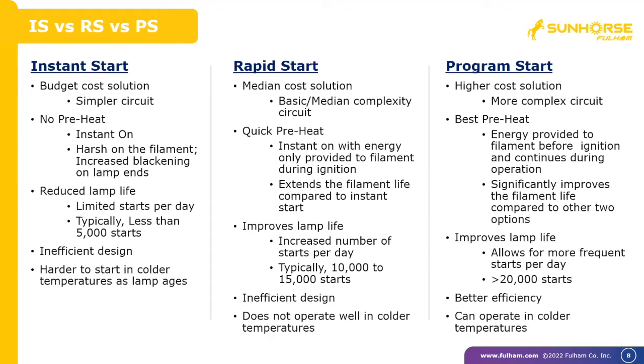Looking at a rapid start type of ballast, it falls more in the medium cost range. However, the benefit is that you get an increased lamp life over using an instant start because of the preheat. However, the preheats tend to only be provided for a short period of time and generally are not as good as using a preheat start ballast, I'm sorry, a program start ballast. As I mentioned, it is improved life of the lamp over an instant start, but it's still not recommended for colder type applications.